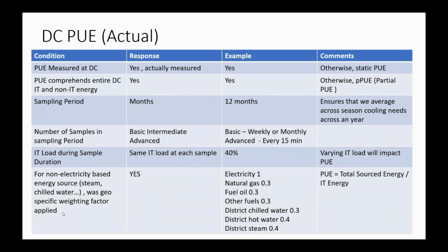Your cooling is not representative of your true cooling budget, right? So if you go through an entire year of 12 months, you've gone through all the seasonal changes, and now you're seeing a much better picture of what your data center is actually doing, as opposed to measuring just the favorable months for you, whatever they are. So yes, absolutely, we have to specify that.